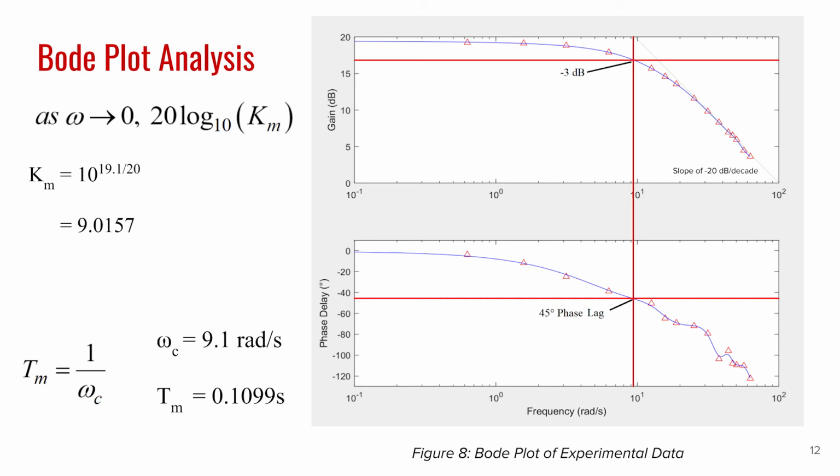The result for the frequency analysis we see here is expected because physical systems often represent low-pass filters, which is seen in this Bode plot. This is because physical systems have inertia and momentum, and these properties can't be changed instantaneously. Therefore, at higher frequencies, the gain of these systems begins to fall off as a result of the output not being able to change as fast as the input.